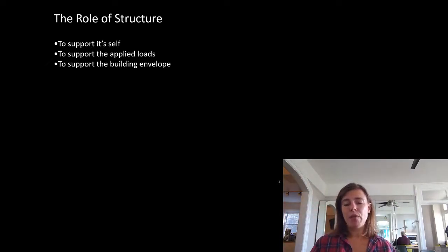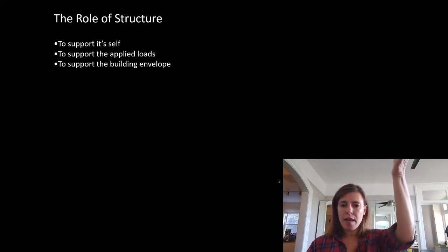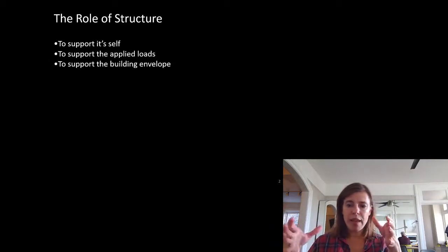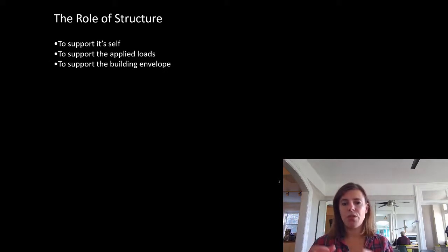I had a friend say, how can they do that? How can that floor, as they come down the floors in the building, taper away? Doesn't that building want to tip over? And I had to explain that the columns haven't changed. The core hasn't changed. They're just used to seeing all that being hidden by the building envelope. And their perception is that the building envelope is the structure itself.